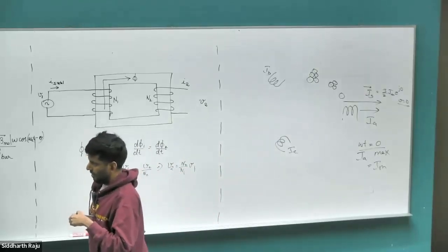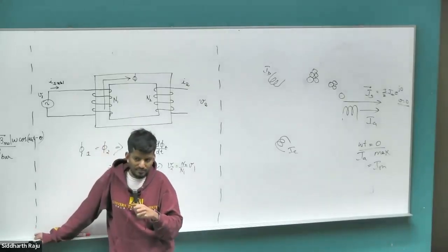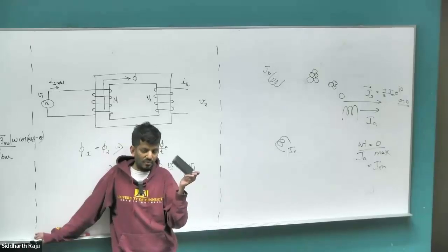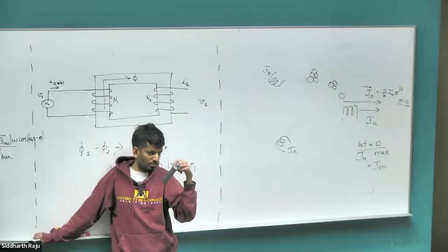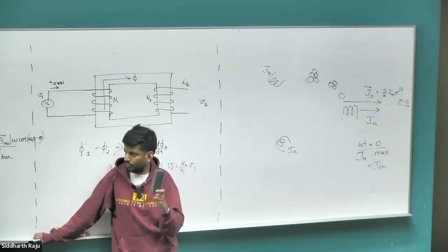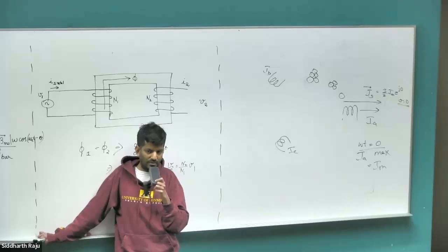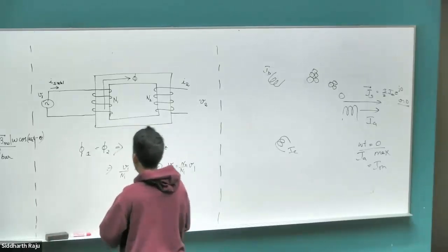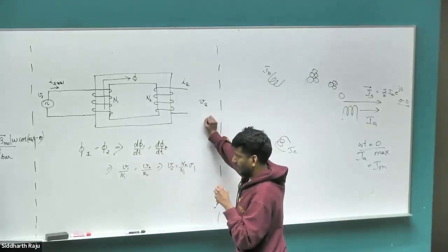Okay. So before we proceed on analyzing what the magnetic field due to the current is going to be, is that rotor current going to set up a magnetic field in the air gap? In case of a permanent magnet synchronous motor, I could measure two distinct air gap magnetic fields. One due to the stator currents and one due to the rotor currents. Take a guess whether the rotor currents on the induction motor will have its own distinct magnetic field as well.